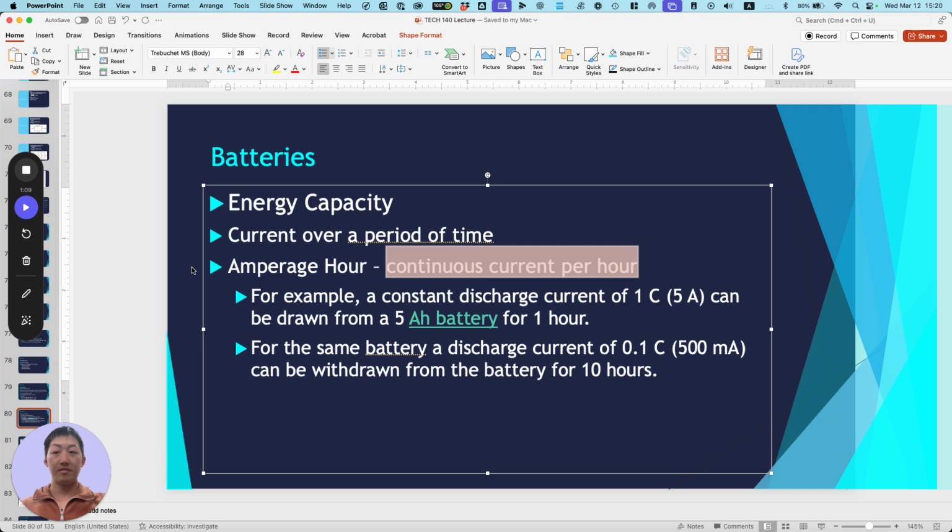We are plugging in to the positive. That's going to be the port number 4. Then the negative is going to go like this, and that's going to plug here. This green cable is plugging here, which is effectively the same as plugging to here. Do you see that? Because they are bridged. So when you measure between 3 and 4, you are measuring cell number 3.